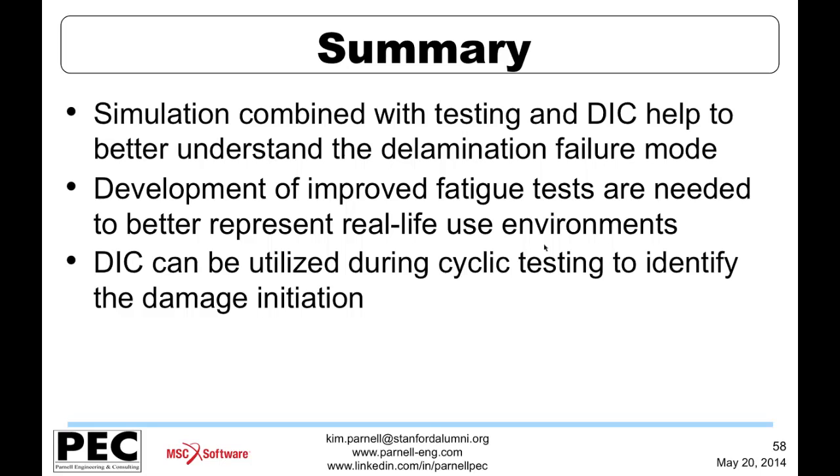So just to summarize some of the things that we've talked about today, particularly we've talked about simulation and comparison with experiment or test through the digital image correlation. That can give a really good understanding of results and validation of results and models, and can also open your eyes to additional types of failure modes that may be important to look at.